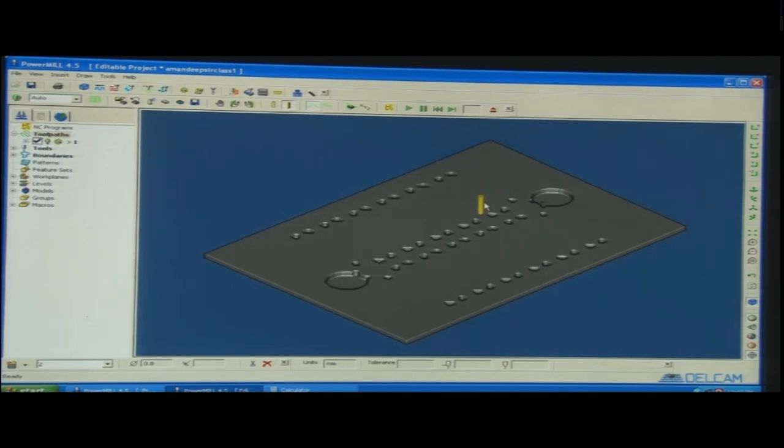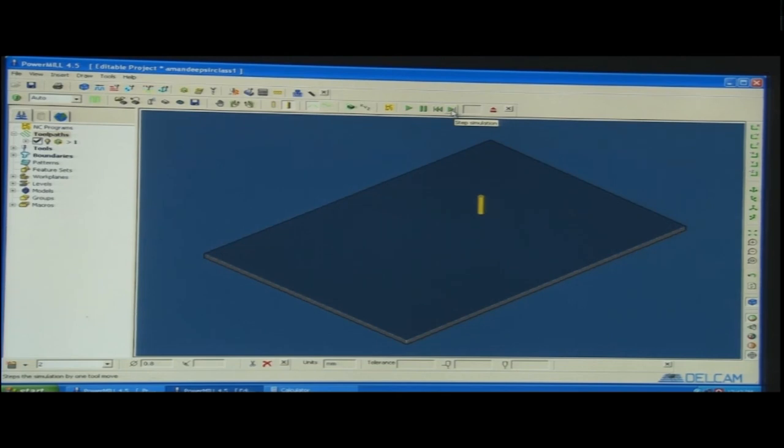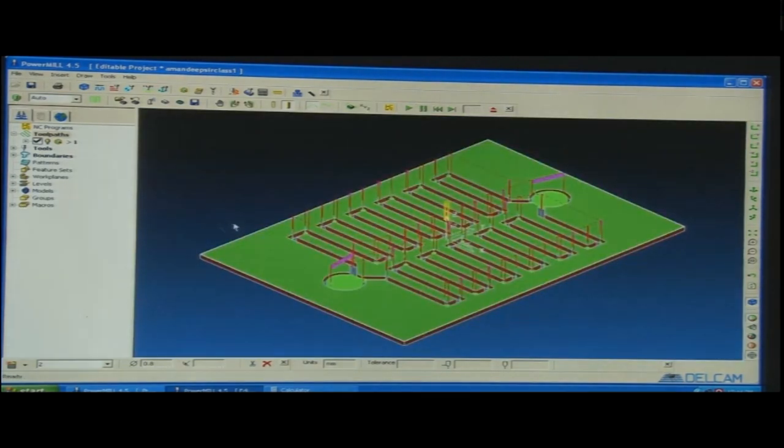So, lead in and lead out is being shown here. See the simulation again, stepwise: 1, 2, safe height is 5 mm, tool reference 3, now 3 mm and 2 mm, yes, now it has entered. Now, it is machining, then lift it up, lead out, then lead in, then lead out and so on, complete machining again. Okay, complete machining, complete plunging action.